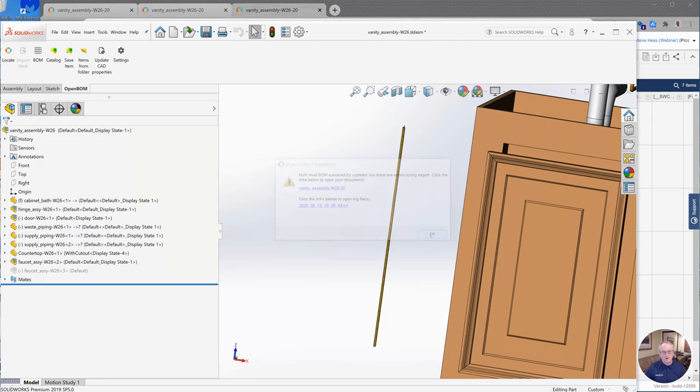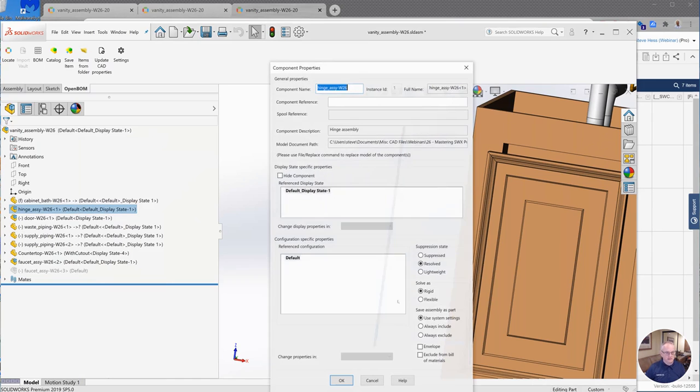It does require that you have write access to the hinge subassembly. So I like using method number two if I have write access. If I'm consuming maybe an assembly from one of my colleagues, maybe a pump or something else, and I don't have write access to it, I can still get that same purchased assembly behavior by using the envelope feature.